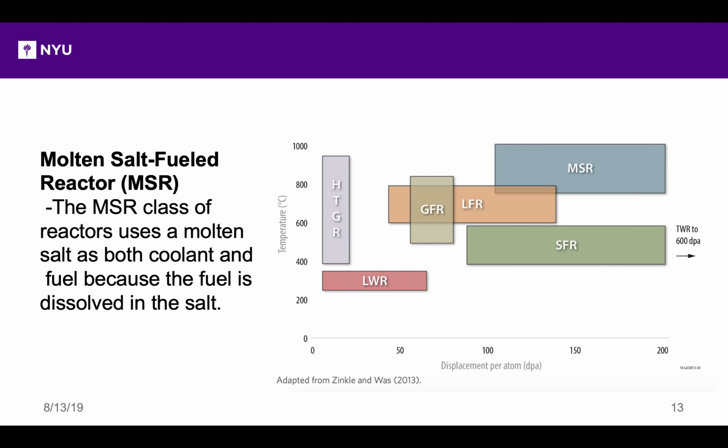A high level of displacement damage, high dpa, challenges a material's ability to perform its function in the neutron environment. This level of displacement damage can determine the lifetime of the component, which may have to be replaced once that level of damage is exceeded. New radiation-resistant materials may be required to accommodate damage levels in excess of 200 dpa.